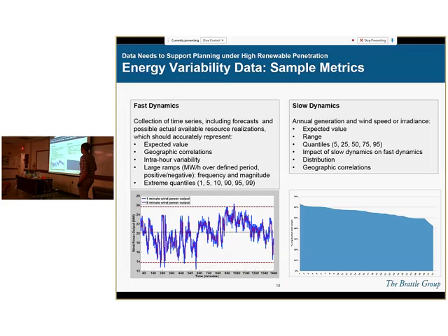The expected value of the wind output is just one, and the intra-hour variability is not being captured if we don't look intra-hour. These large ramps can be very important. We've had blackouts that were arguably caused by large ramps in the wind, and if we fail to capture such things in the transmission planning, then those events have a huge amount of value that's lost, value that the transmission could bring. And then also the slow dynamics, thinking about the wind output over the course of a year and other slow dynamics that can be integrated into the wind planning process.